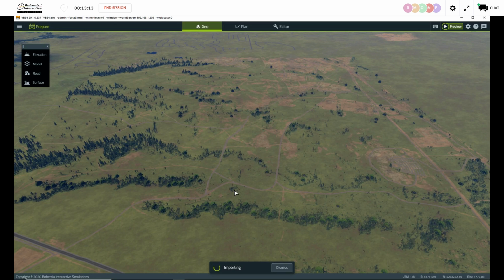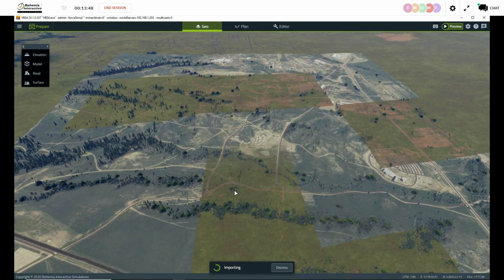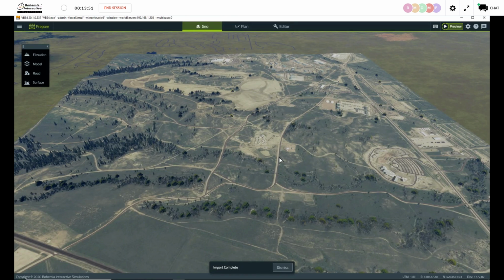And just while we're waiting here, it's going to take about a minute to get this import process done. I'll just point out the difference between VBS Geo and TerraTools. So VBS Geo is perfect for these relatively small area terrains. We haven't actually put a hard limit on the size of the data you can import using VBS Geo, but typically, because it's a what you see is what you get tool, I'm guessing kind of 5x5, 10x10 kilometers, depending on what exactly you want to do. And then you would use TerraTools from VBSim to build out bigger areas like geotiles or many geotiles, or if you wanted to modify the way the procedural generation works, then you would use TerraTools.